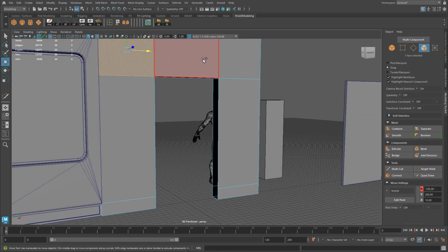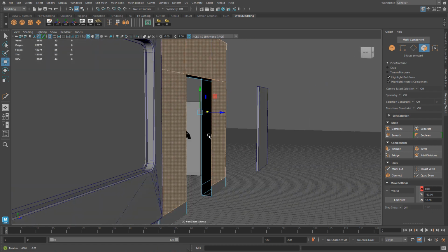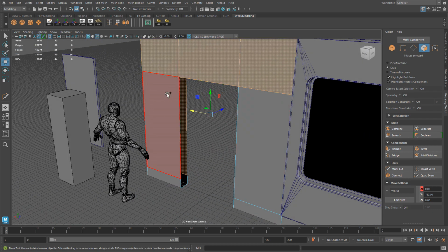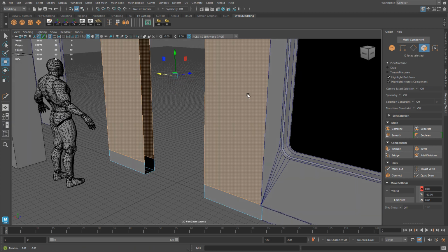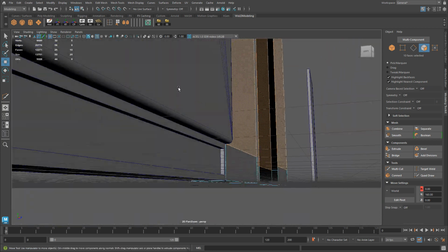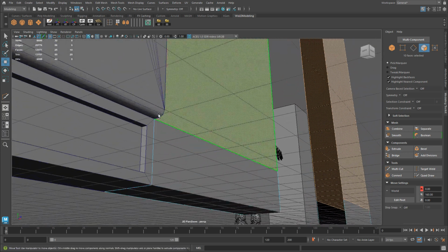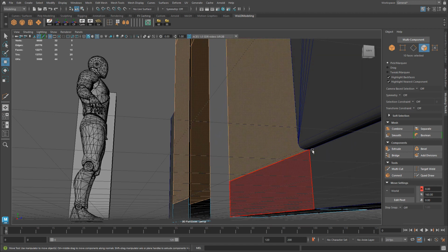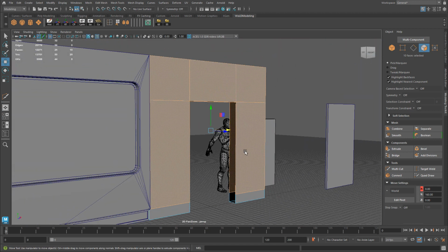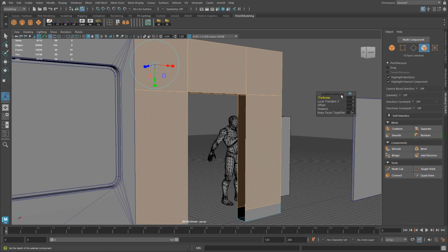Let's select the faces in the front and the back, because I want to have the same type of extrusion being done for the front and the back, so it matches this curvature right here on both sides. So I'm going to extrude all these selected faces. Control E. The thickness of this, since I already did the wall with the window, I know exactly the dimensions that I need to do for everything else to match up. So my thickness is going to be set to 4.